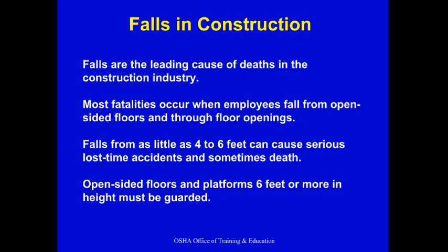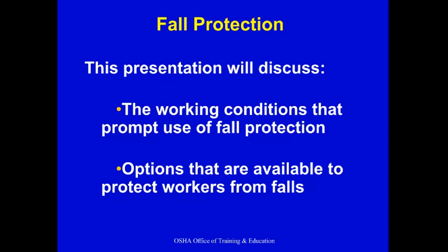So if you look at the very top of a door, you could just say to yourself, anytime I go above that height, I need to have fall protection. Anytime any part of your body is below it, then you're safe. But if you're above that door height, then you need to be sure that you have some kind of protection so you don't fall and hurt yourself.